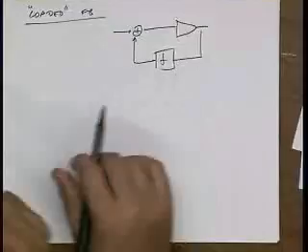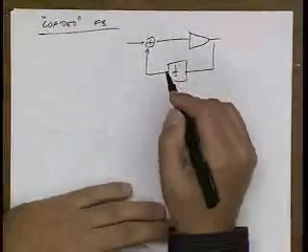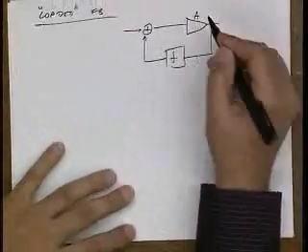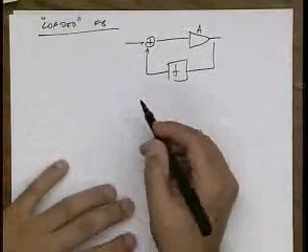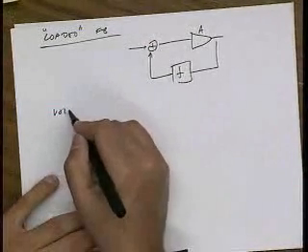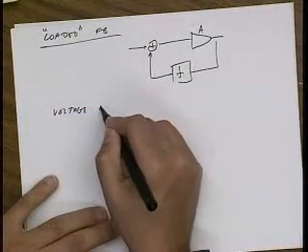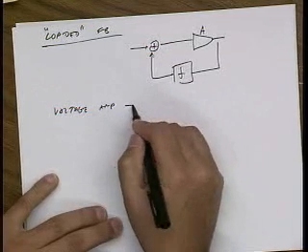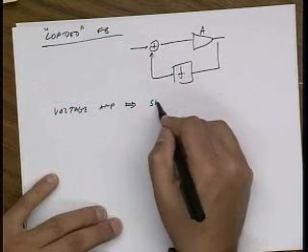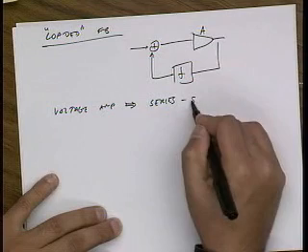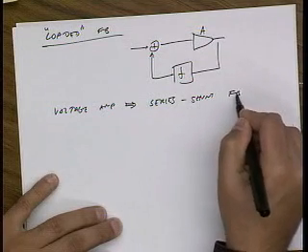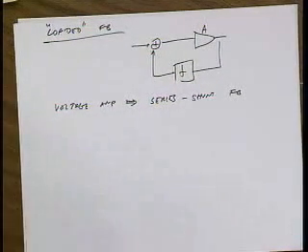Okay, and this is a signal flow diagram. Let's say I'm interested in a voltage amplifier. So that means that I want to have series shunt feedback. I want to sample the output voltage and subtract an input voltage.